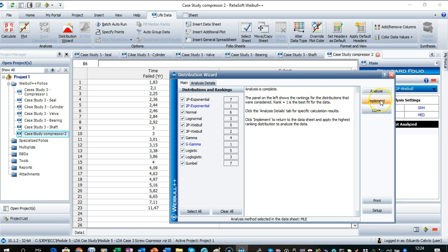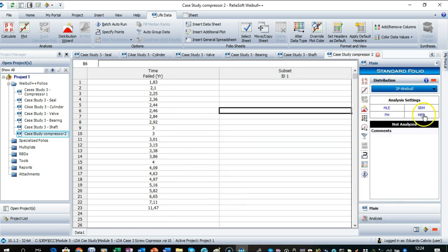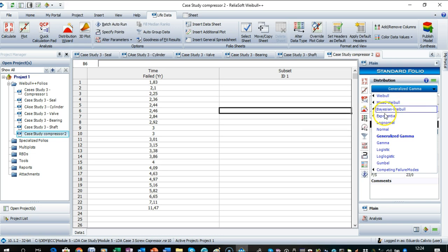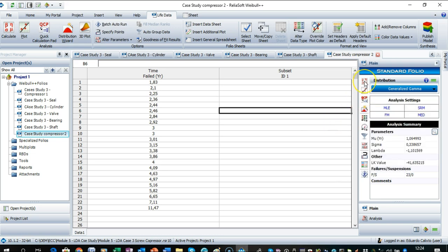So when we mix all these patterns, we expect to have an exponential PDF, but we have some gamma 2 parameters here, and the gamma shows that there is a specific period of time in which we do not expect failure. So let's use the exponential PDF 2 parameters, and then let's compare both reliability functions. So here we are. What the gamma says is that until 1.3 years we have 100% of reliability.